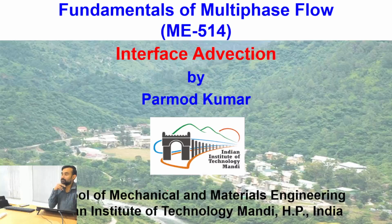Okay, good morning. So we have been talking about interface reconstruction in the previous lectures. Now we will specifically talk about interface advection. If you recall, particularly for one-dimensional flow, we have already studied interface advection, and there we first talked about the piecewise constant upwind scheme, then the piecewise linear upwind scheme, where we found that the slug gets diffused to multiple cells once we used these two schemes.